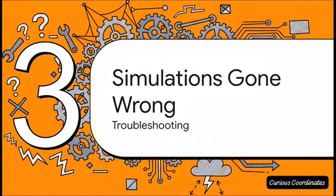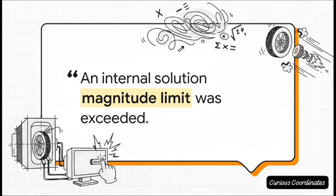So, what happens when you build the model, you set everything up, and the simulation just fails? Picture this. An engineer spends hours, maybe days, setting up this model of a wheel. They hit solve, feeling good, and then this cryptic message pops up. An internal solution magnitude limit was exceeded. What this really means is that the whole simulation just broke. A part of the model is mathematically just flying off into space.